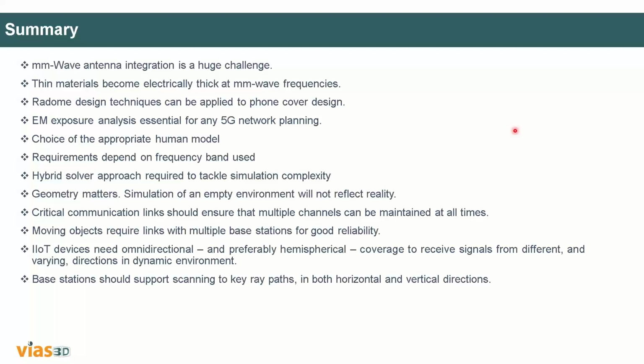So what you have seen is we have different kinds of solvers, and selection of the solver is very important. You can do the multiphysics analysis of the particular structure. You also have a design studio which is equipped with different kinds of components, and a hybrid solver to get acceleration, and different methods you have seen for the antenna array. What are the methods? One is using the unit-cell approach, or a sequential simultaneous design approach, or the DDM method.